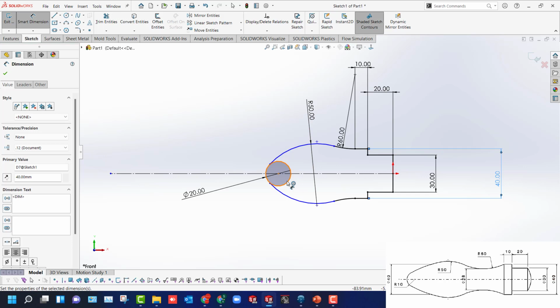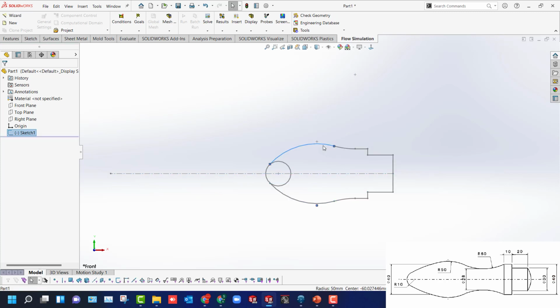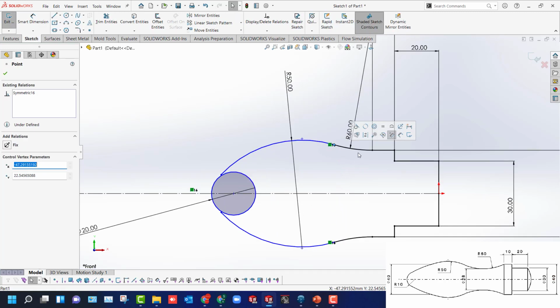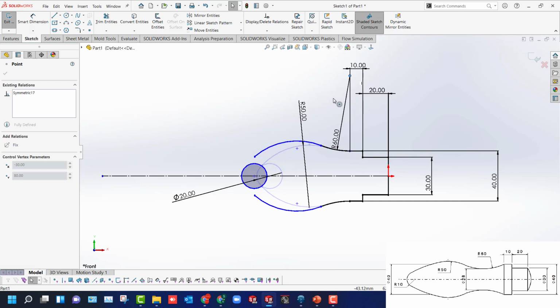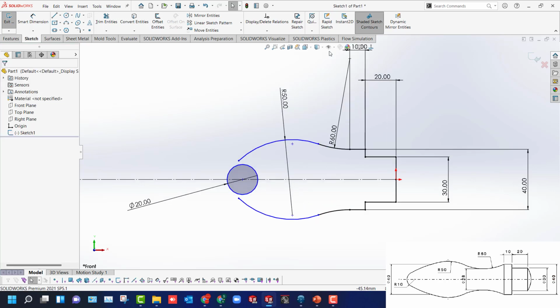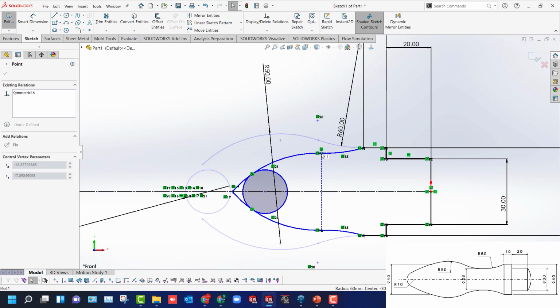To compensate that one, what I can do, if I move it, okay, you can edit, double click on the sketch to edit it. No, I can't move it. I'll activate the relations actually. They're confusing. Yes, so the tangents relation I should remove. Right? It is not exactly tangent. I'll remove it. Now if I move it downwards, yeah, it will.